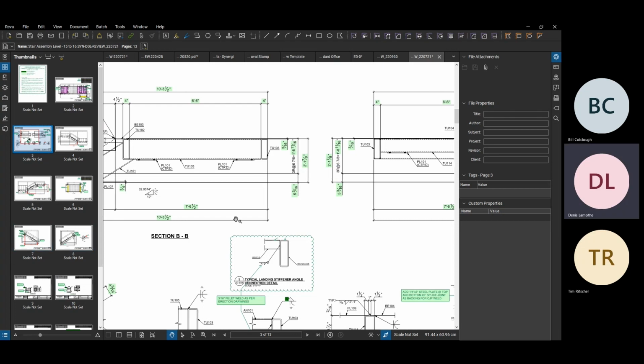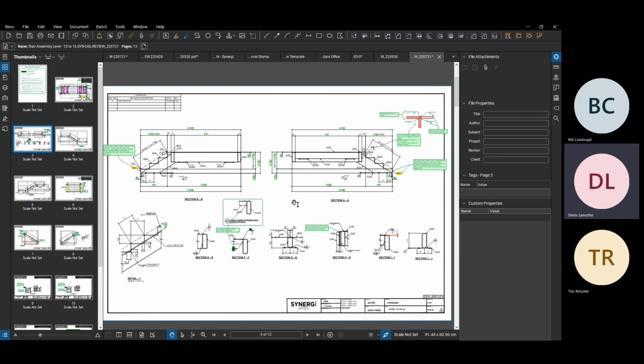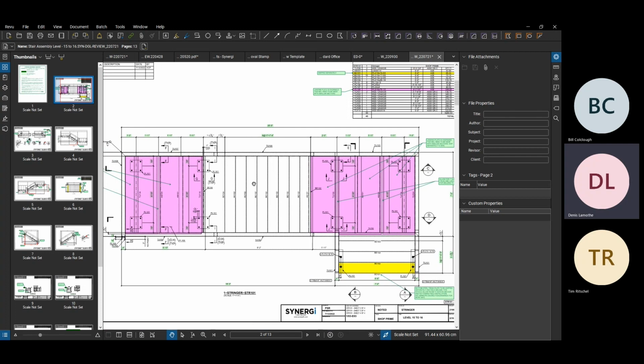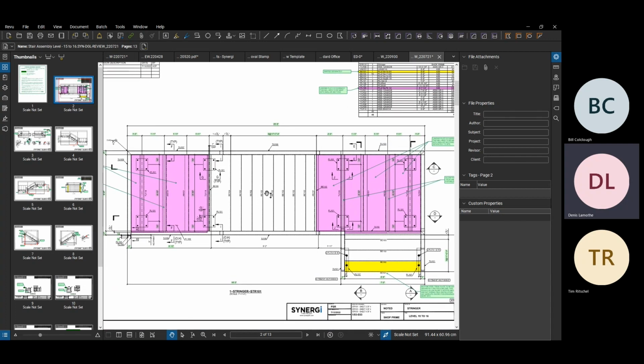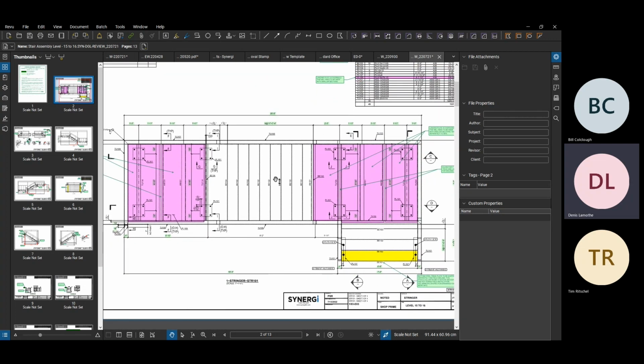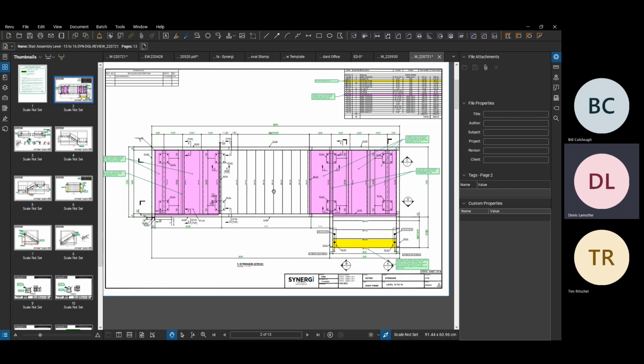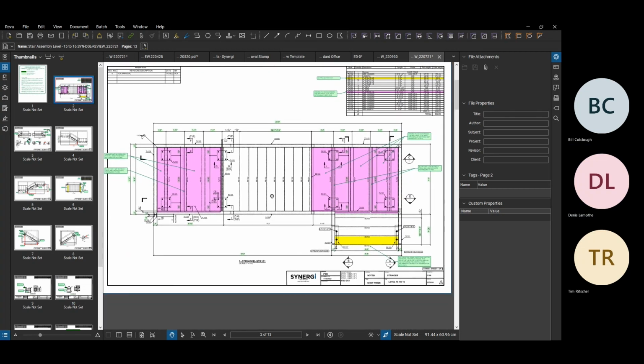And the last thing, kind of obvious to most, is just make sure that there are enough dimensions on the drawings that the guys in the shop know how to fabricate it and are able to put all the pieces where they need to go. If in doubt, ask yourself, if you were tasked with putting this together, do you have the information on these drawings to fabricate or install it from the parts that would be given to you? If the answer is no, you don't know where you would install this tread because you don't have a reference point, then you would know to add a note saying that we need a dimension to this point, or we need more information as to where this is located.